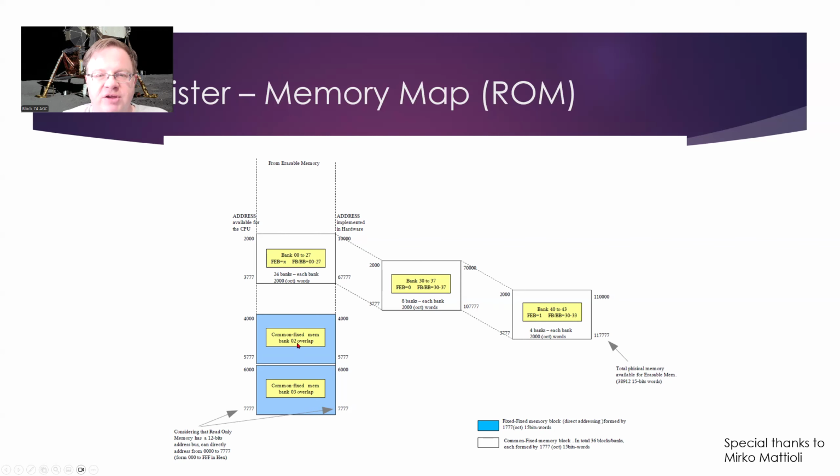We're going to have to figure out how to use the contents of the lower 10 bits of the S register and the E bank to address our static RAM that we're going to be using for the Apollo Guidance Computer replica. And then we're also going to have to figure out how to decode the 12 bits of the S register, as well as the contents of the F bank and FEXT, or the fixed superbank, in order to map those to the addresses that will be stored in our ROM chip.